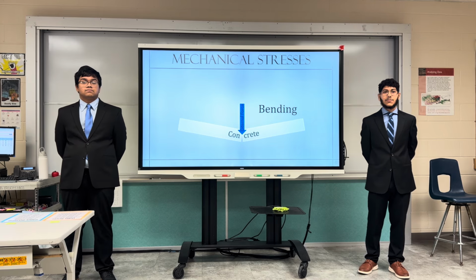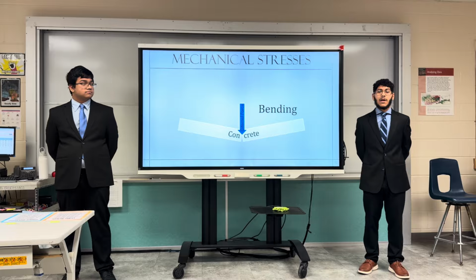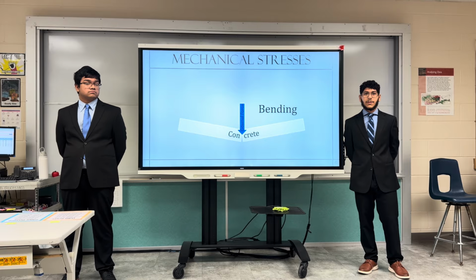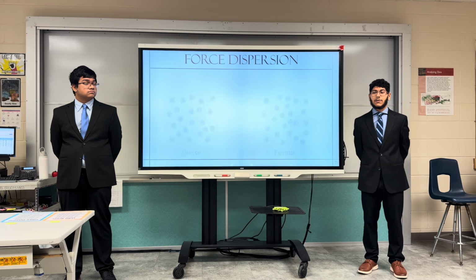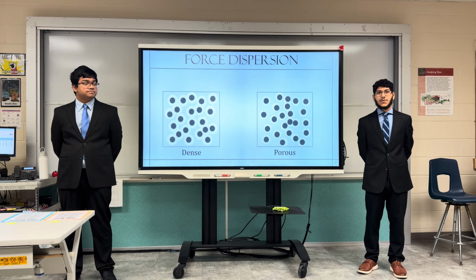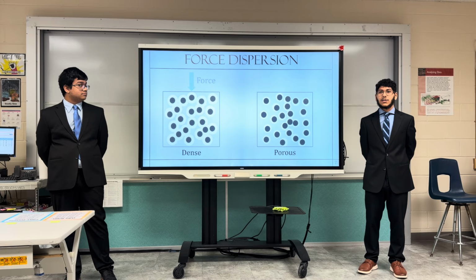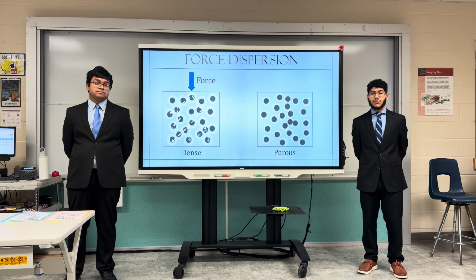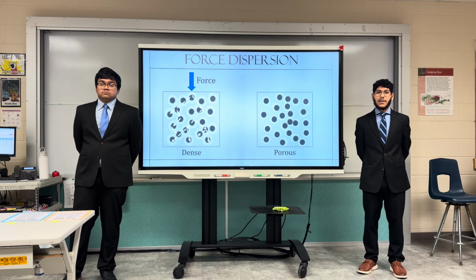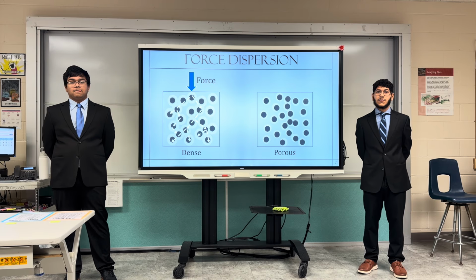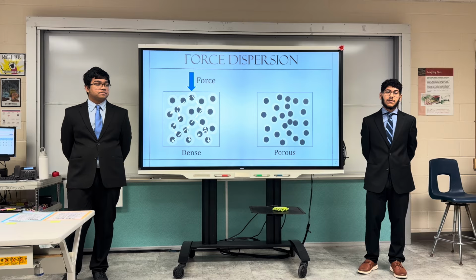Whatever has the greatest resistance to the stress of bending will have a greater force withstood and thus flexural strength. And the stress resistance is determined by the internal microstructure of the concrete. This is because when you have a well-developed microstructure, as there have been a lot of chemical reactions filling in, the microstructure is dense, so when force is applied, the force can evenly disperse throughout, allowing less concentrated stress and thus more force withstood before breaking, thus a greater flexural strength.